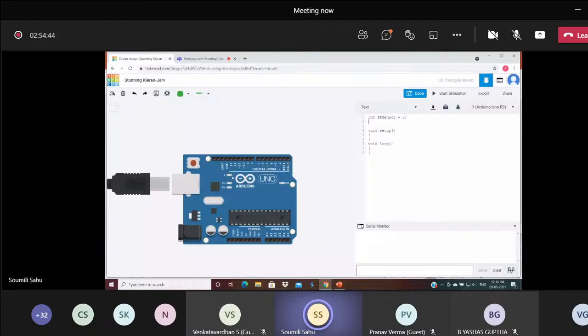So we will use that to switch on and switch off this LED, so that we can know whether the object is detected or not. We know that it is internally connected to the 13th pin, right? We read that.